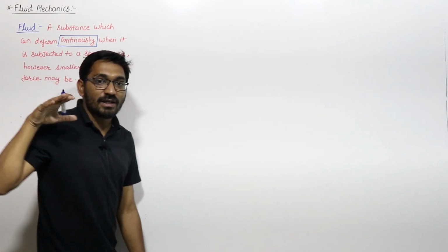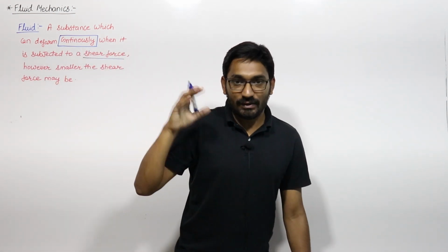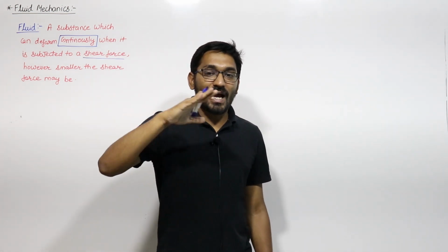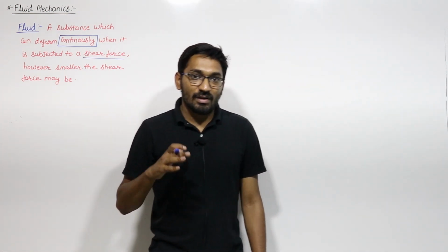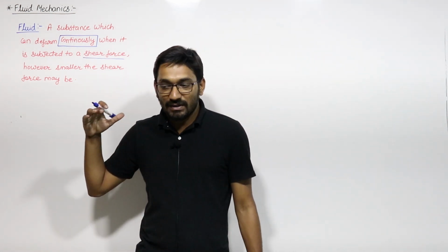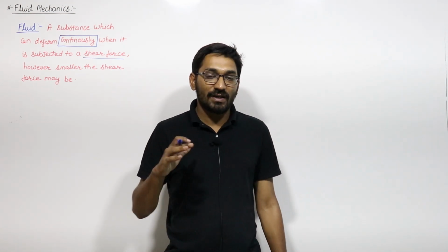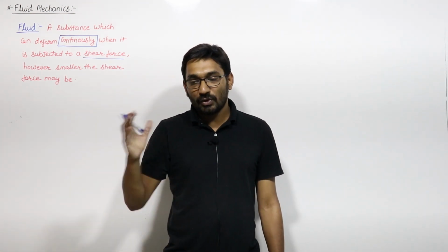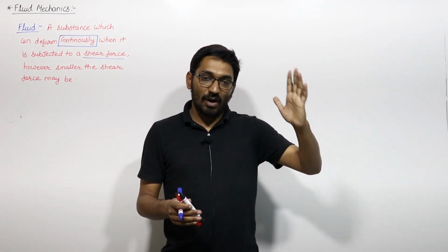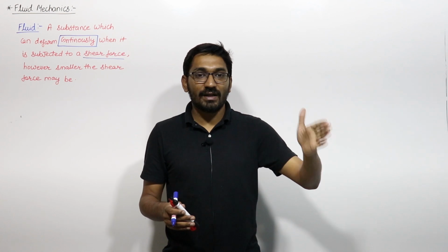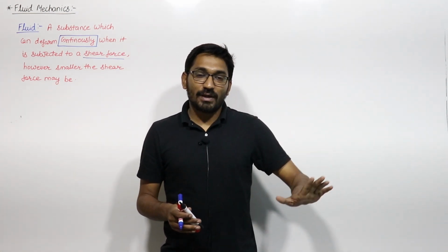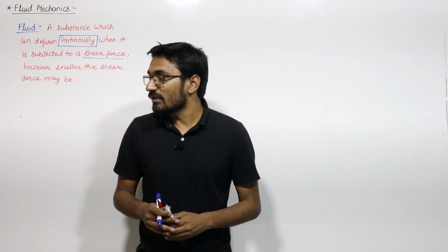This is important: fluid will deform continuously when it is subjected to a shear force. If you apply a shear force on a fluid particle or a fluid, then it can deform continuously as long as that shear force is acting. If that shear force is acting for, let us say, 10 seconds, then it deforms continuously for 10 seconds, and when you remove the shear force, the fluid flow will stop at that point only where you removed the shear force.